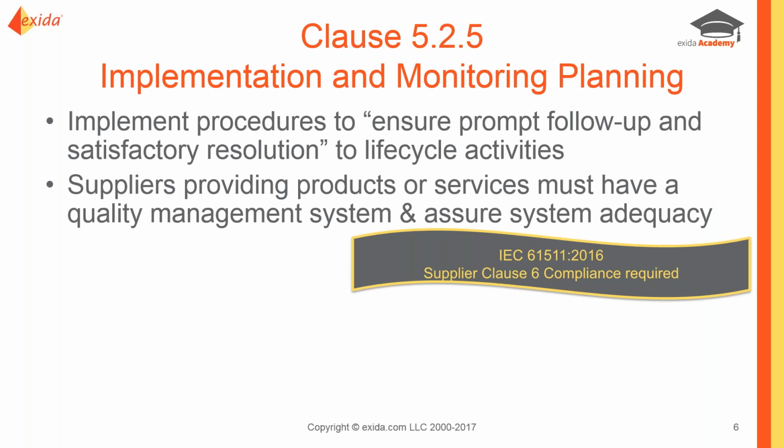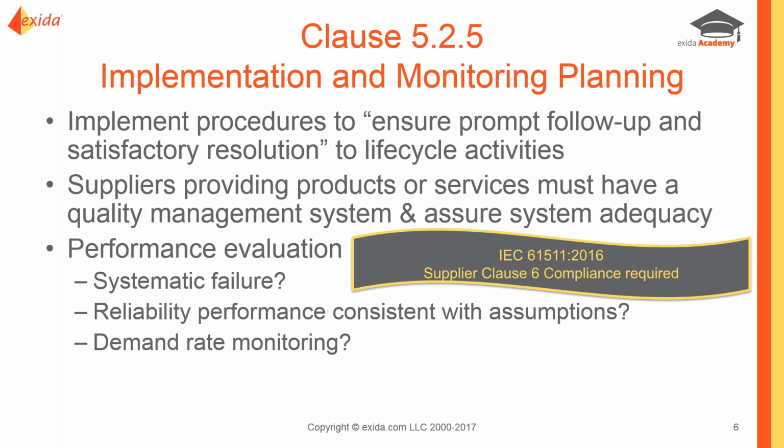The standards have been out for a couple of years now, and there's a new version of IEC 61511 that came out in 2016, and it has placed additional requirements on supplier responsibilities and the compliance that they need to have. So if you're using suppliers to provide either products or services through any part of the implementation of your life cycle plan, then we need to make sure that they meet the appropriate criteria.